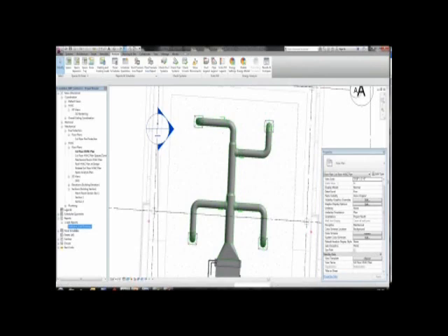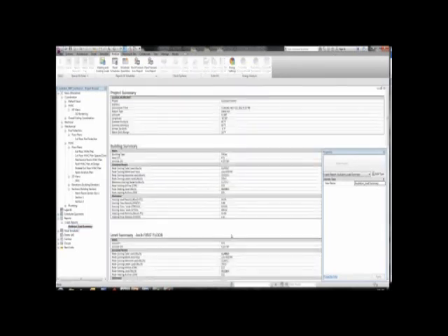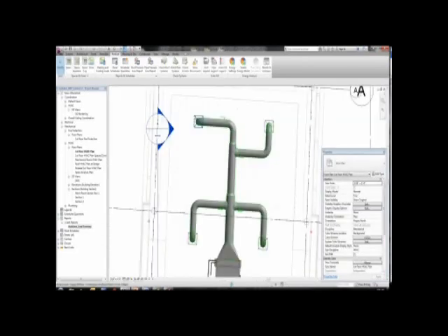So if I just go over to my load reports, and we just take a look inside of that building summary, you can see that for that particular room, that FCU1, the CFM there is 513 CFM as specified under the calculated load. So as I close out now, I can take advantage of actually getting that 150 CFM per diffuser in by going and editing the room calculation point.